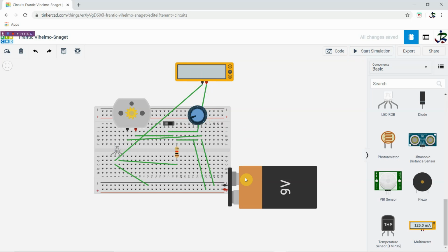So make the project. First you do this project by yourself, and then we'll add to it. We will add one more RGB, one more motor, and one more potentiometer and switch, and we'll control two motors, two RGBs and potentiometers, and we'll check the voltage by multimeter, mainly voltage, not ampere and resistance, because mainly for troubleshooting we need to understand what voltage we are having at the motor, the LED or the potentiometer. That we will understand with the voltmeter, and the other connections we can consider.